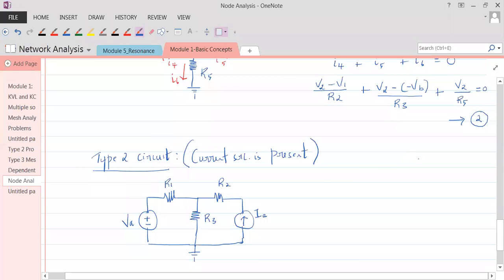See, this circuit can be written as this is R1, this is VA. This is R3. There is a resistor. There is a current source. This is how the circuit is. So there is just one non-reference node. This is anyways ground. Understand that? And the resistor R2 is redundant, not of any use because it is in series with the current source.